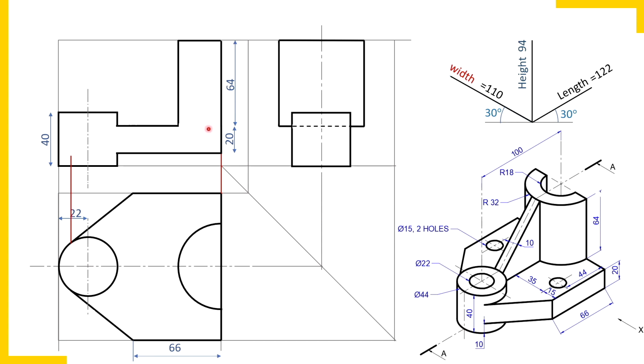The boundary between the two now will not appear here. The reason is this portion is removed and now what we are watching here is one single plane, and that is the cutting plane, the surface in the cutting plane. Similarly, here the two lines separating cylinder and plate have been erased. So now this is the section. But smaller details we have not yet drawn.